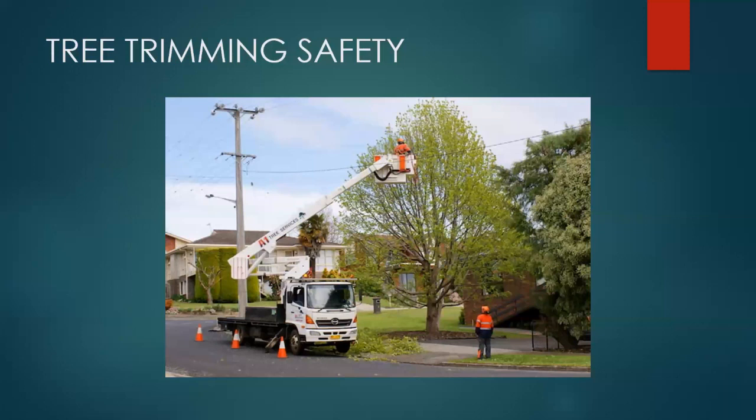When aerial lifts are used for tree trimming operations, ensure that they are maintained and properly set up for use, used according to the manufacturer's instructions, not used as cranes to lift or hoist tree parts or material unless designed for that purpose, and only used with fall protection equipment, including tie-off.